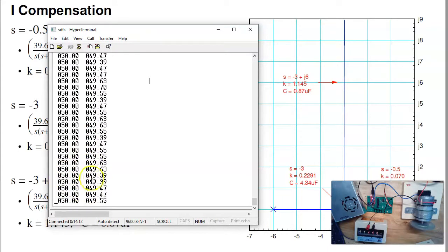Okay, notice there's almost no error. There's a slight error because op amps have slight DC offsets. If I tell it to go minus 50, it takes about 8 seconds to get there. And in theory, it ought to be dead on. Not quite, because there's apparently a little bit of resistance across that capacitor that's discharging it.